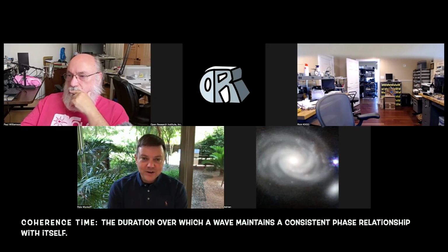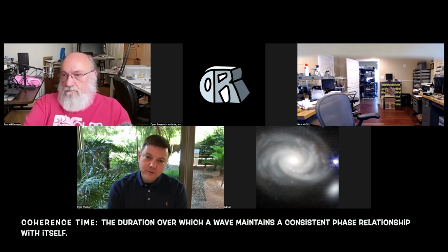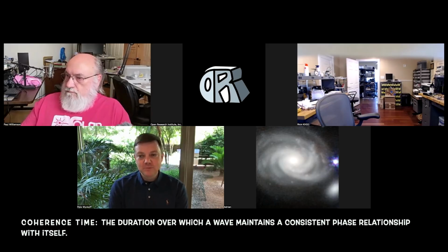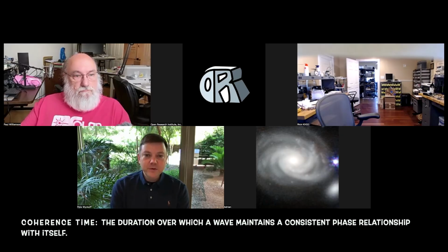But the idea of coherence time is not really defined by channels, it's defined by channels and waveforms. And that seems to be the cutting edge of delay-Doppler channels and OTFS and that sort of thing. So there's hope that the coherence time of channels like EME is longer than simple approaches would say, because we can prove for simple channels at least that we can get longer coherence time by taking different views of the channel as delay-Doppler instead of just time-frequency. So maybe there's hope there, but to say it's a heavy lift might be a gross understatement. We'll just have to see.